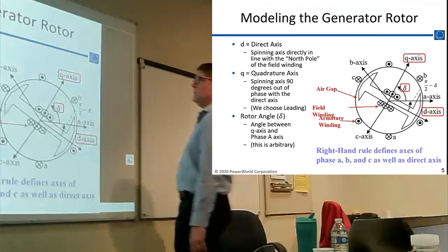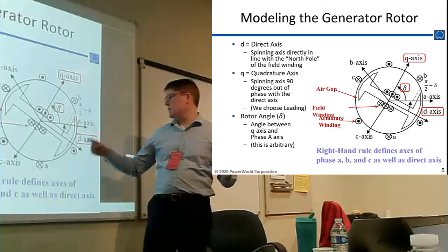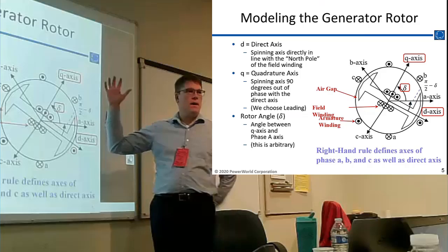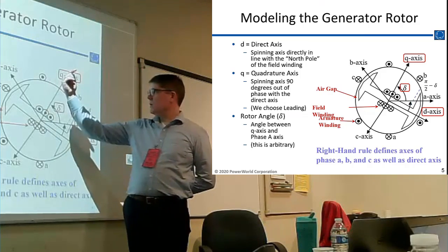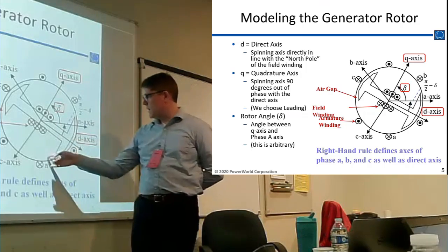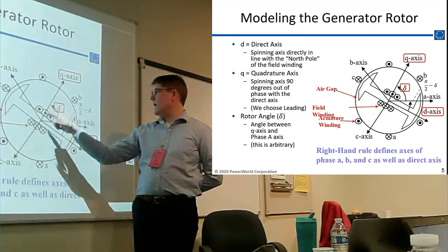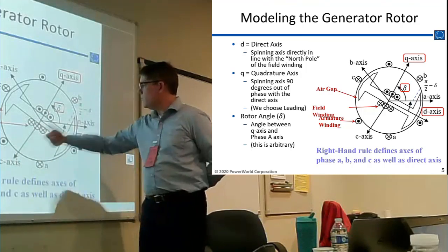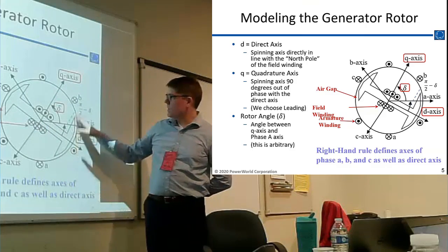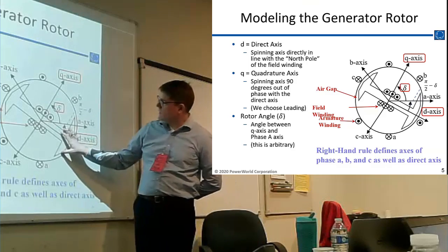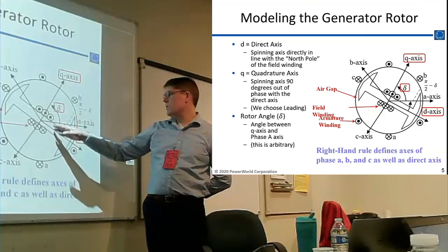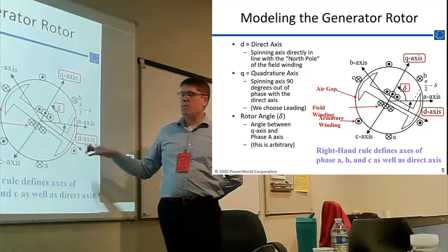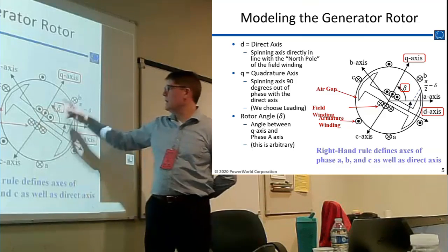So, all right, to start with, let's just assume we have a 2-pole machine. So we have A phase, the dot and the arrow, these represent windings. If you remember, make sure you use your right hand, put your left hand behind your back. The arrow's coming out here, so we have current that's going like this, kind of down the armature, up and back out. And we create the A axis then with the right hand rule from that. The B axis is right here. It's going like this, so the B axis is up this way, and you can draw these positional axes that way. And then finally in the middle we have a rotor. The rotor winding is coming, the arrows are going in and out this way, so the D axis is in this direction. All right, from there, the D axis is related to the rotor, and these A, B, C are related to the stator, or the armature on the outside.